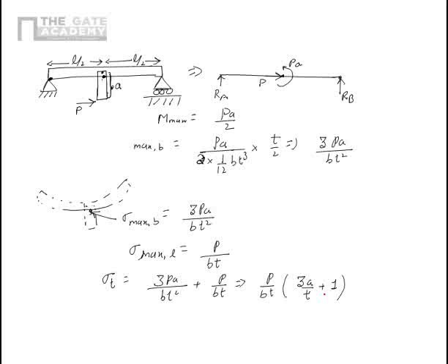Now obviously we can make problems more complex, but the phenomenon doesn't change. It may be a case of multiple loadings, but for each loading we can figure out the stress because of bending and because of the longitudinal force and add them up algebraically to figure out what is the maximum normal stress in the beam.